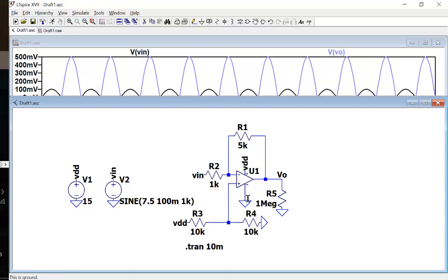And we are talking about zero, the ground, as the bottom rail right now. It's different from the negative voltage. This is the ground at the bottom rail. We need to lift it here for the non-inverting terminal, and we need to lift the signal from the function generator. Just go to the DC offset option of the function generator and change it to 7.5 volts. You have to do it on both sides.